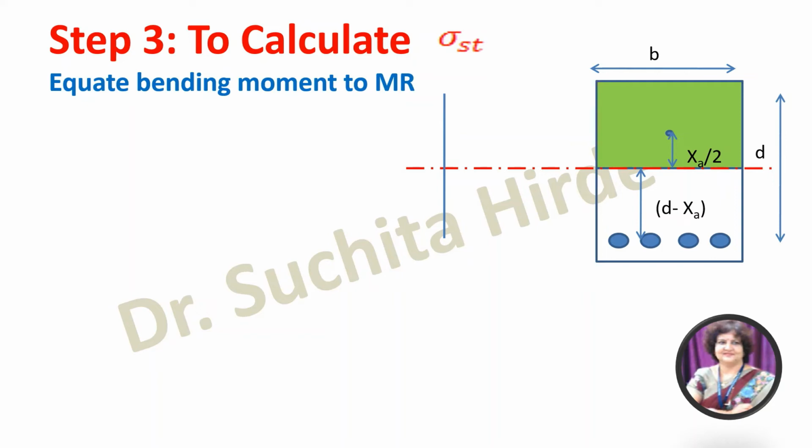You know that the stresses are maximum in concrete at the top. It is like this, and this is what we want to calculate. And you know that towards neutral axis the stresses reduce, because at neutral axis there is no stress, stress is 0. So this is triangular variation in working stress method.